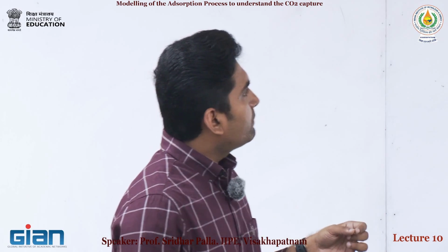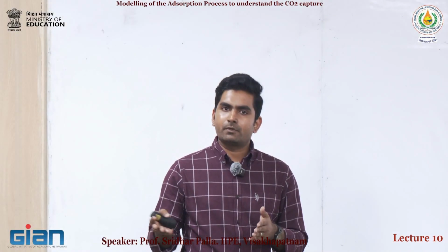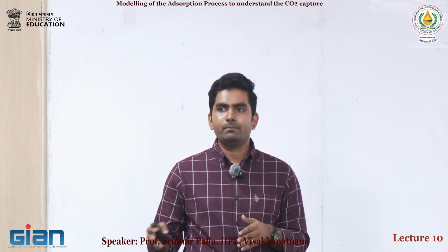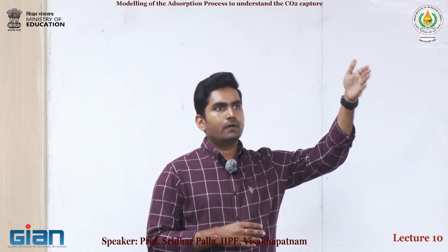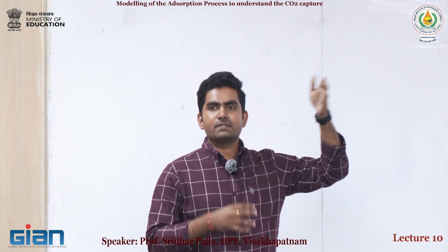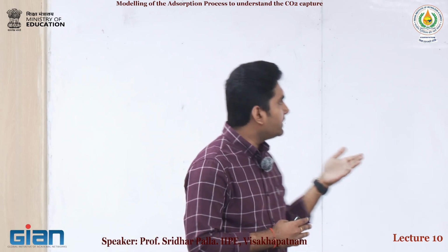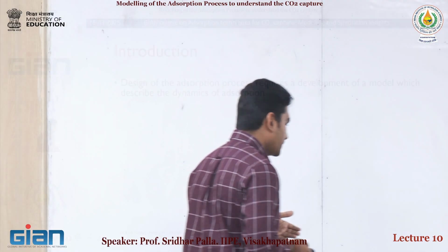So what is the dynamics of adsorption? That means how the concentration of the adsorbed gas changes, and if it is an exothermic process, the temperature change that takes place in the bed, how the temperature is changing with respect to time, and also the pressure, how the pressure will change from inlet to the exit, and how it is changing with respect to time. All those various conditions, how they change during the process, is called the dynamics of the adsorption.